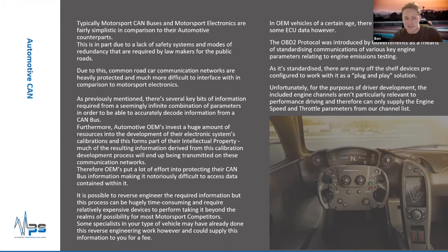Unfortunately, with our application here of wanting to monitor and improve a driver's performance on track, they only really focus on engine channels, engine parameters. So it's a great simple solution for us to grab the engine speed and your throttle position, but it won't offer us a solution to monitor the driver's input on the brakes or the steering angle, for example.